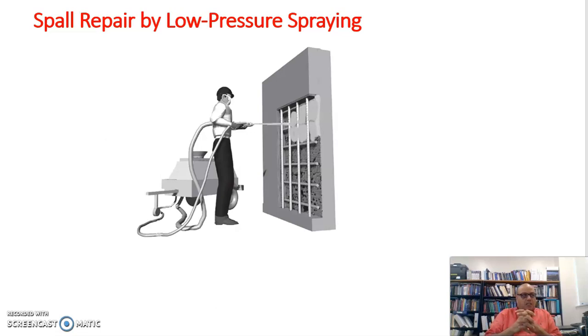You can apply it using a small concrete pump or heavy-duty grout, and you can force this grout into the cavity. And you need to make sure that the new material is going to bond to the substrate, and that can be achieved through proper surface preparation, the low velocity impact of that method as well, and the material properties of the mortar that you are using.